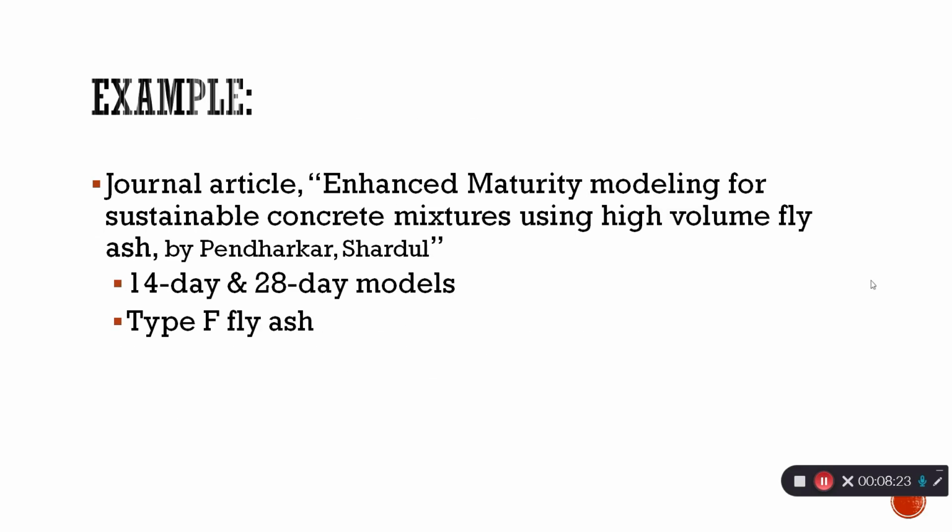So our first example is from the article Enhanced Maturity Modeling for Sustainable Concrete Mixtures Using High Volume Fly Ash. It focuses on the 14-day and the 28-day models when looking at a concrete mixture, and it focuses on type F fly ash primarily. It observed concrete mixtures in 14-day maturity models with 35% of type F fly ash, 50% of type F fly ash, and 35% of type C fly ash.